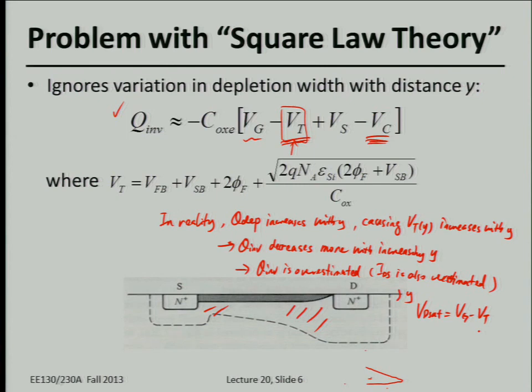But in reality, if you make the correction for depletion charge, because this is underestimated, you're going to have more depletion charge, okay? The consequence is, if you look at the position of the pinch-off point you derived with the approximated approach, in reality around that location you're going to be over-depleted, right? You're going to have more depletion charge.